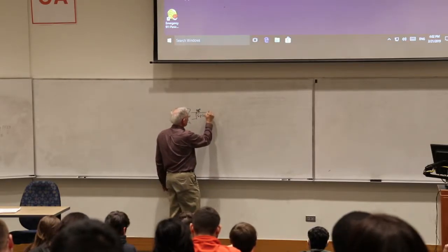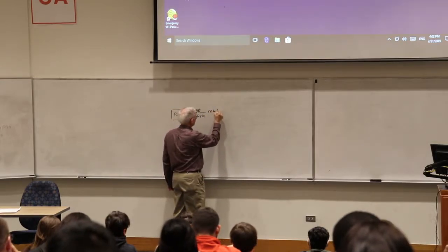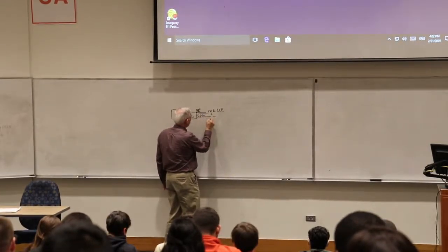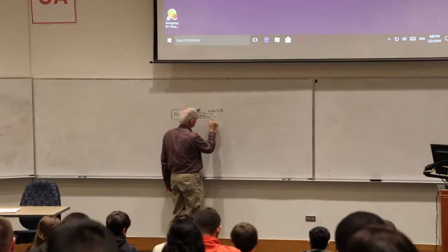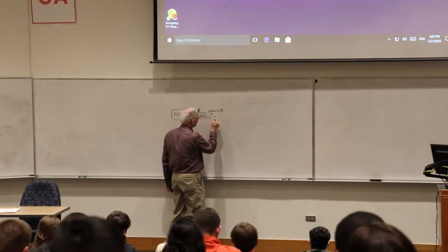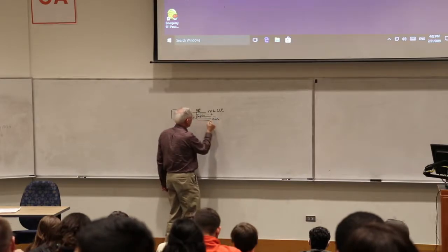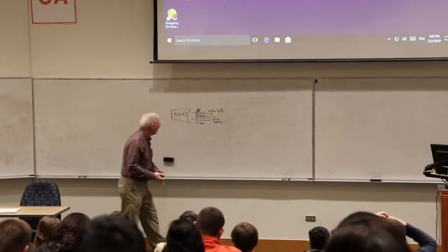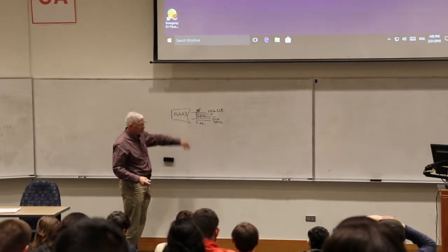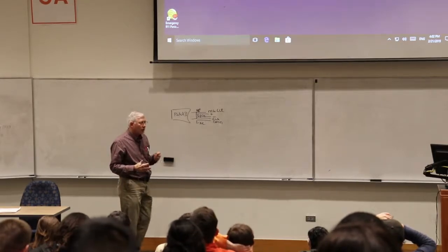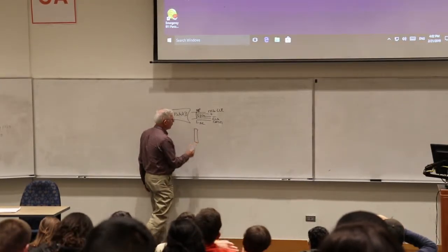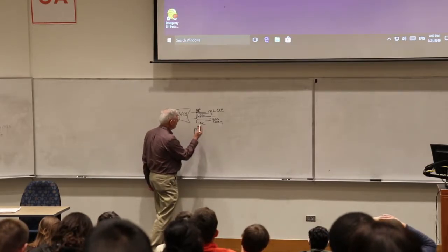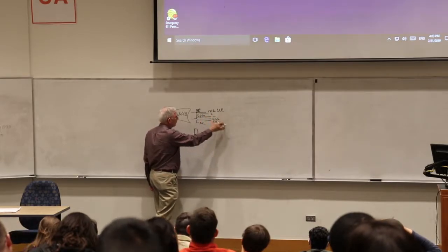That pin goes to the master clear. Then you have power, ground, and then the clock, which is the debug clock, and then the debug data. Then you have one pin that's not connected. That's the 1, 2, 3, 4, 5, 6 pins. Now, the Snap has 8 pins, so that in itself is a little confusing. But the first 5 pins are the same: master clear, power, ground, clock, and data.